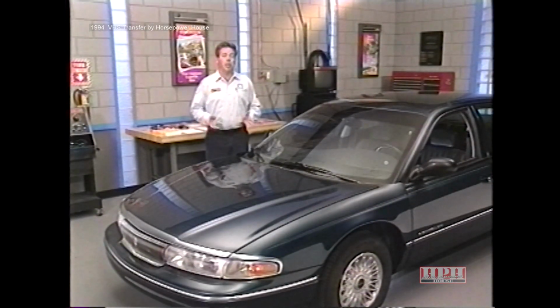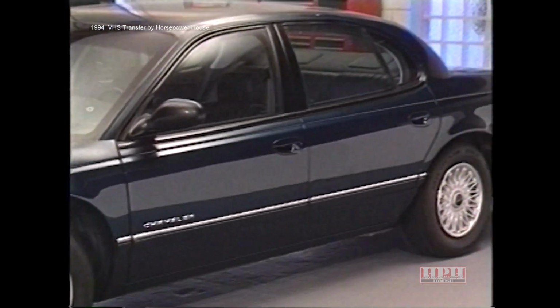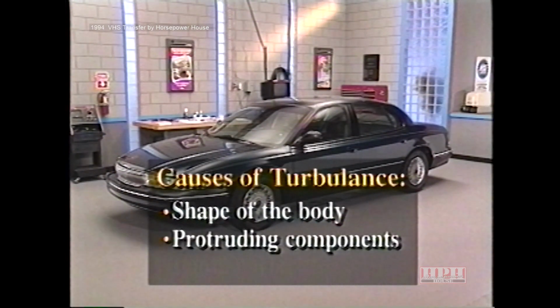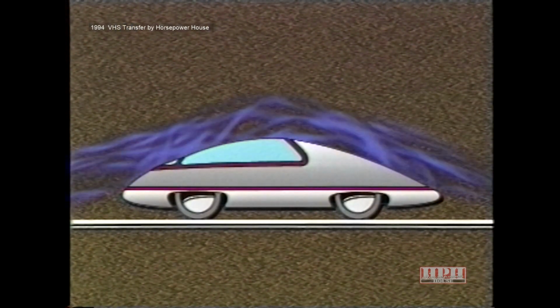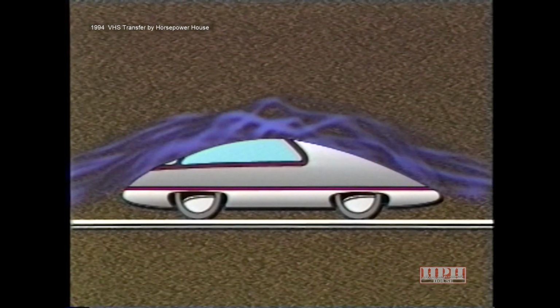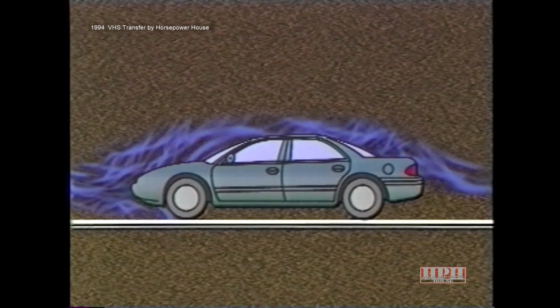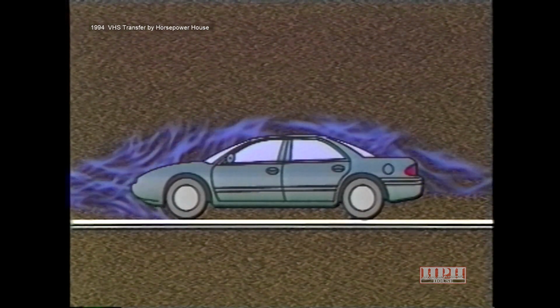Basically, wind noise problems can be categorized into two groups: those caused by turbulence and those caused by air leaks. Turbulence can be caused by anything that disturbs smooth airflow around the body surfaces. The shape of the body, protruding components, and loose parts can all cause turbulence. A completely streamlined body would produce the smoothest airflow and reduce turbulence the most. But such a vehicle would not be very practical. So engineers have created body designs, body insulation, and seals to eliminate as much turbulence as possible.